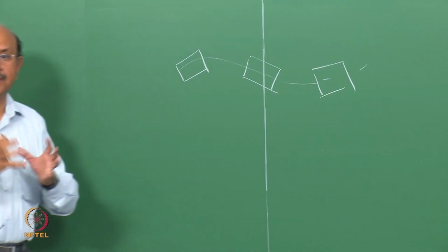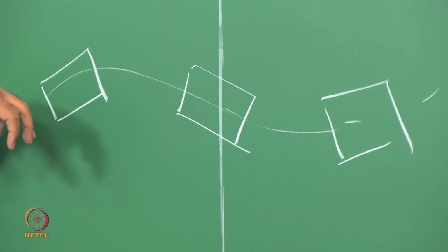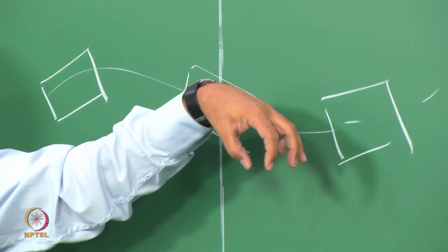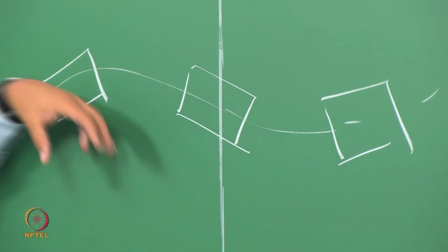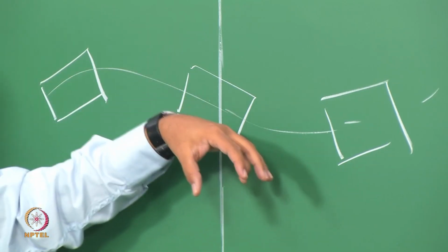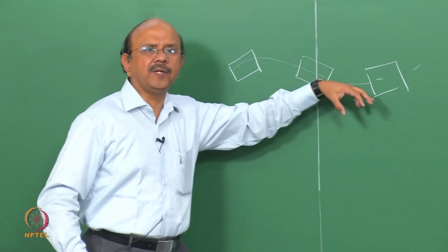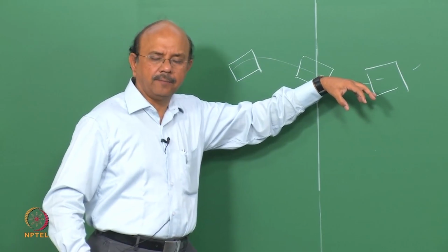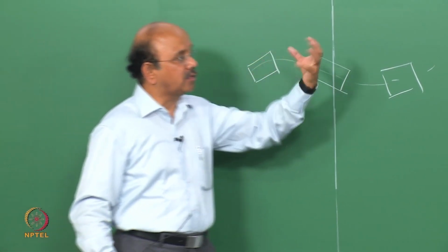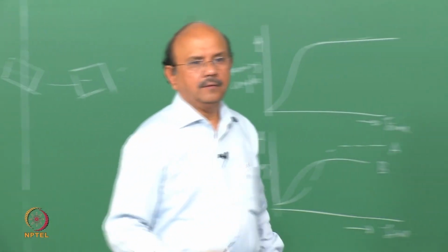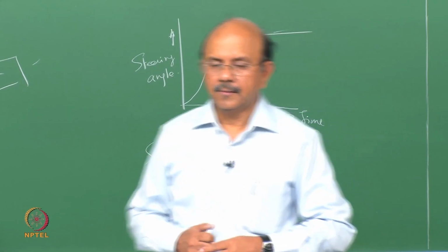As the vehicle yaws, what also becomes important is yaw damping. Does it yaw, how much does it yaw, and how difficult is it to control the vehicle as it yaws? How does the yaw damping bring the oscillation back to a steady condition and so on? That is what we mean by yaw stability. So that's the oscillation around yaw.